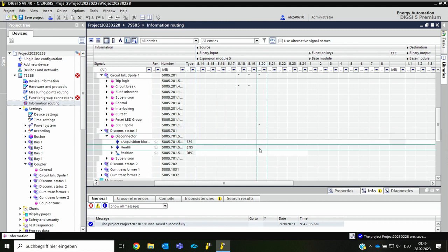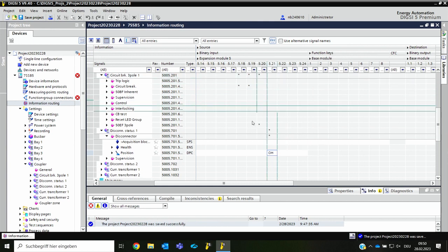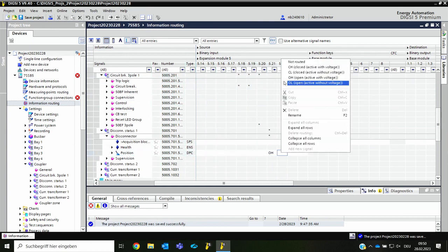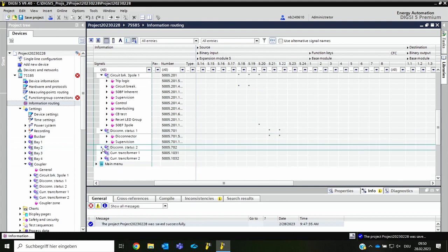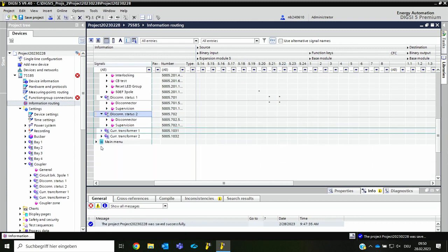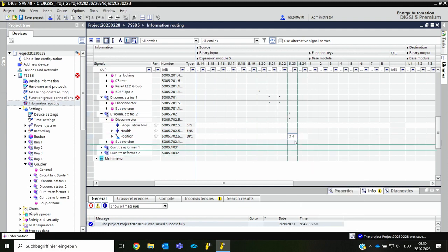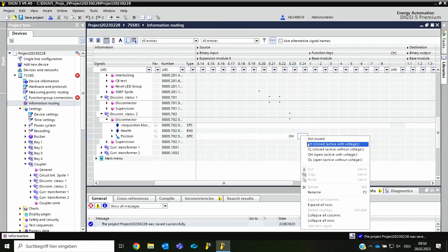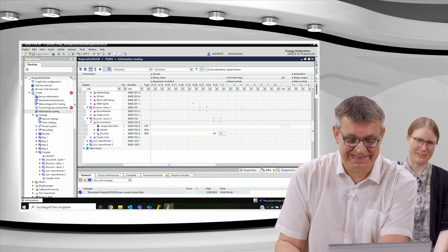And we will continue with the disconnectors. Disconnector position, open high, closed high. Disconnector 2, and position, open high, closed high. So Nina has really tailored the device exactly to what we need. There's really no binary input free anymore. Luckily I counted right.